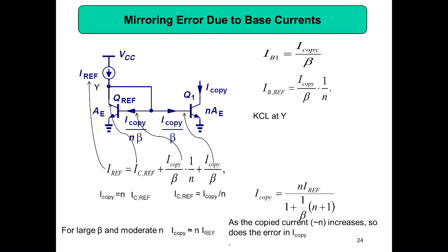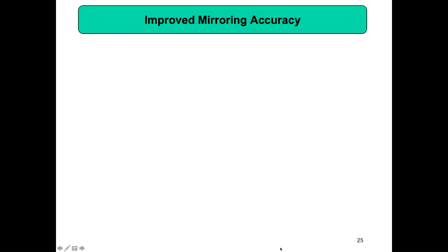And this is a problem with this type of current mirror circuit. So this current mirror circuit has a problem. It means when your transistor number increases, you actually have two problems. When you have more transistors, your error will be more. Secondly, there is also a fan out problem. Fan out means the current you are getting here should be able to power the remaining transistors. That also is a problem. Then how to overcome this issue?